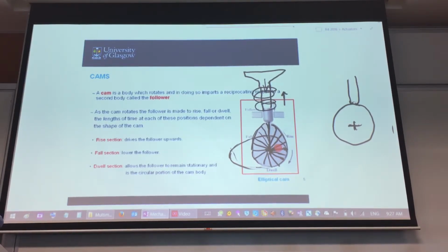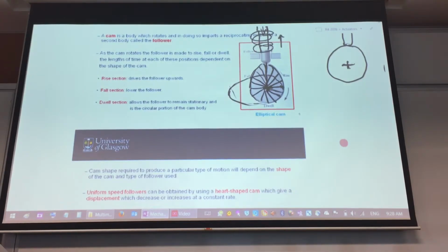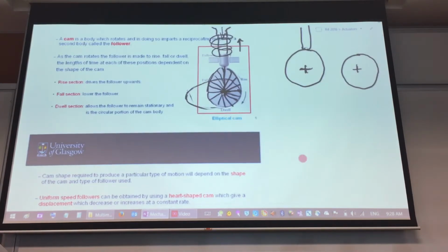So there is this timing of opening, closing, and wait. Open, close, wait. This sort of timing. So we can make use of the various designs of this cam to come up with various different profiles. So a profile of this nature, maybe if I start here, let's see, yeah, maybe start from that way, this egg shape.